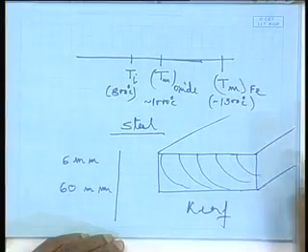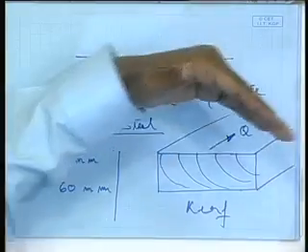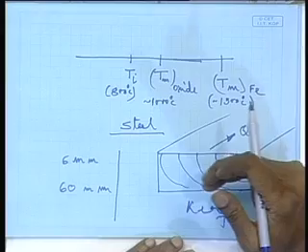The solution is only how to increase the speed of cutting, because that is needed not only for higher productivity, but also higher product quality. I want to have the cut edge better, and also at the same time, if the cutting speed is less, then more part of the plate gets heated up. There is more heat flow in the plate direction. More part of the plate gets heated up, which means there is more probability of thermal deformation, right.